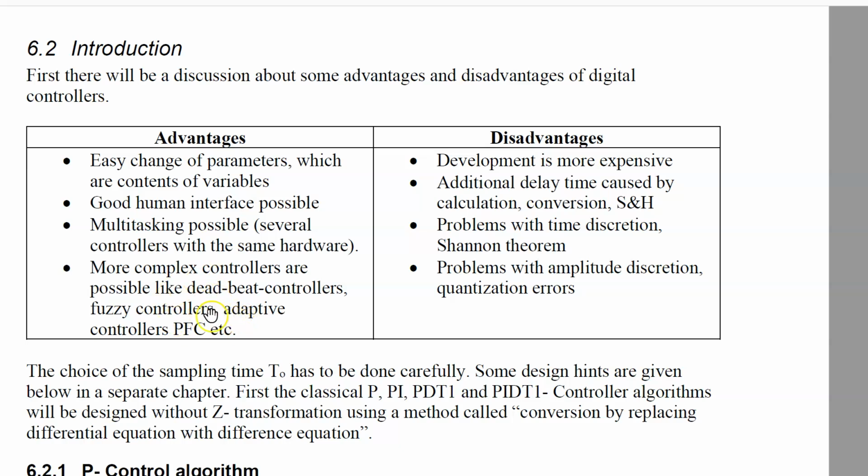Now you can use the controller to measure process parameters, like identification, then make an automatic design of a controller. So adaptive controllers are rather comfortable if you don't want to design your own controllers. The computer can do this job for you. Or finally, you need a computer and digital controller if you want to have predictive functional controllers. You will see in chapter 9 there are some nice ideas, controller methods which are much better than a PID controller. But there are also some disadvantages.